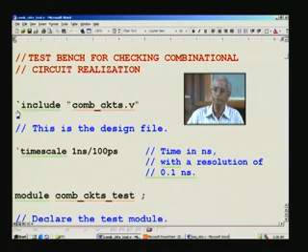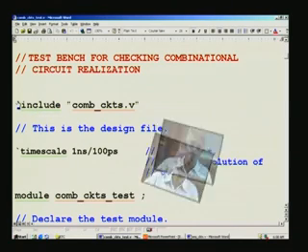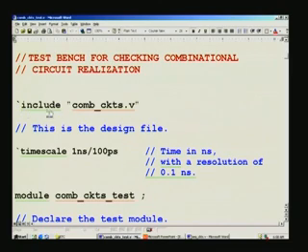This is the very same thing as a C command instruction. We have a tick here, a reverse tick, this is a must, a keyword that you cannot ignore, separated with one or more blanks or tabs, and then put within quotes. These quotes are also required, and note that it is a .v. So, you have to completely specify the file name.